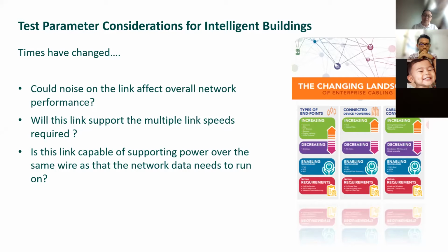As you know, PoE, which we will talk about later, has changed over the years, starting from as low as 15 watts. Now we are going up to 90 watts. Who knows? It may go beyond 90 watts. As PoE increases, as the power running on a cable increases, the temperature of the cable also increases. So that's why there's a lot of consideration. It's not just laying cable and that's it, wash your hands and done. There is a lot to understand about the changing landscape in the market.